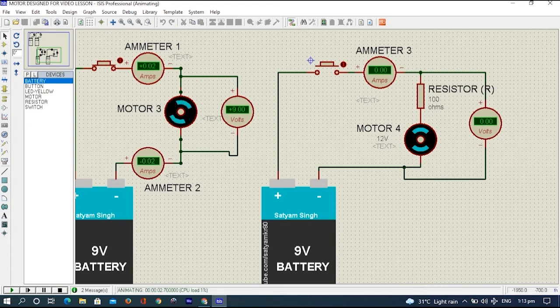Remember, on the third circuit, the speed of the rotor here is quite fast compared to the next, but we do not know yet. Let's run the simulation first. Now, our circuit here has a current flow of positive 0.04 amps with a voltage of positive 8.99 volts, and the speed of our rotor here slightly decreases, because we have here our external resistance.